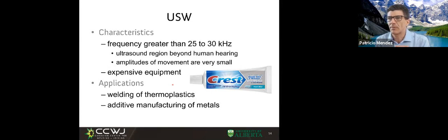I have a question here about the linear friction welding that asks, how do we clean things afterwards? Yes, in friction welding or linear, it's not filing, you machine it. Those parts are machined afterwards. Not grinding. Okay, so the amplitude of the movements are small, but the equipment is relatively expensive. Again, this you justify when you need to weld like 50 million toothpaste tubes, not when you need to weld one.